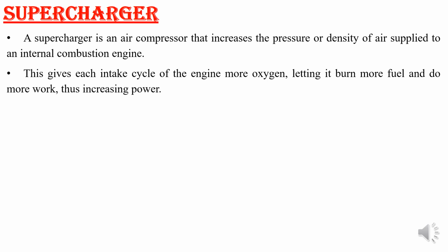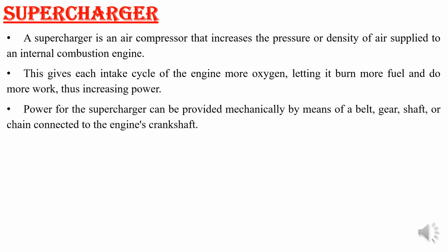The power of the supercharger can be provided by mechanical means, that is belt, gear, shaft or chain connected to the engine crankshaft. We are using this compressor, and it is a power input device, so we should give it power. How to give the power? It has to be given from the engine itself, from the engine crankshaft; some amount of power has to be transferred to the supercharger.